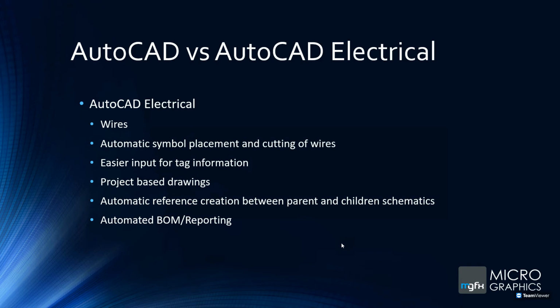Out comes AutoCAD Electrical. With AutoCAD Electrical, the line you draw is actually a wire. So it acts as a wire. It'll have a gauge, it'll have a color, it'll have an area to it. And that is all created in the wire layer that you have as well.